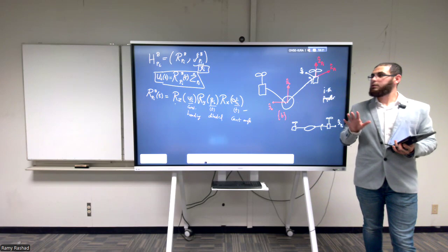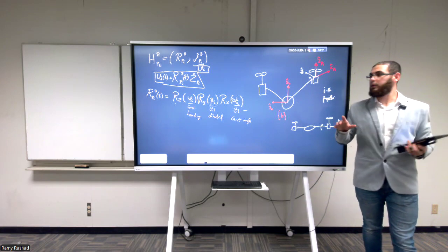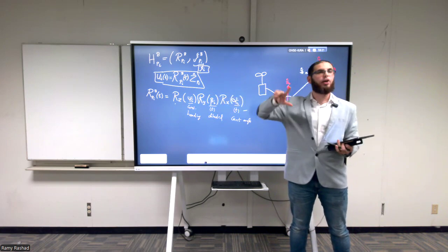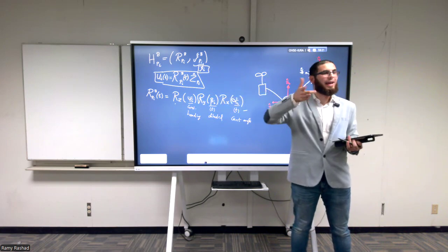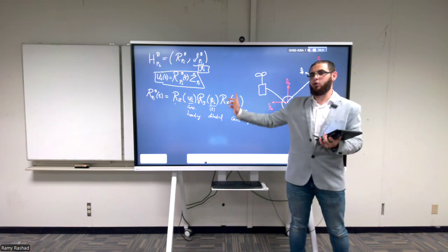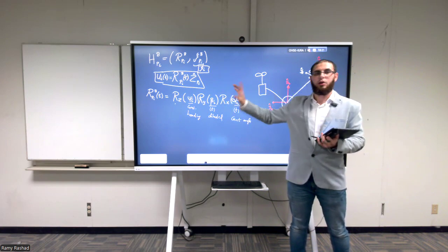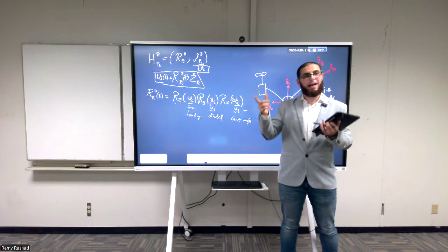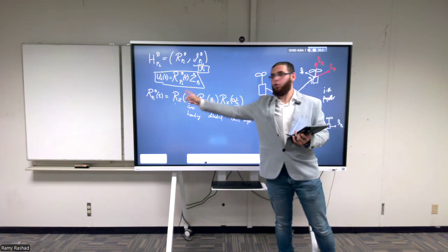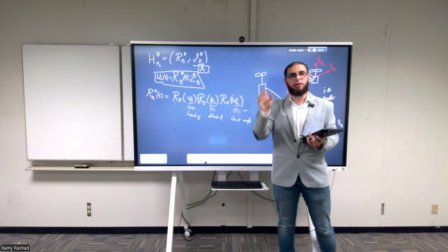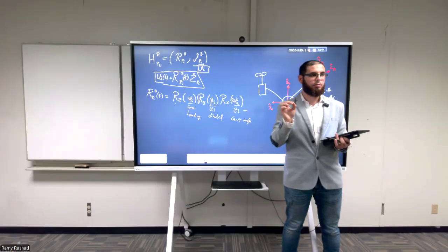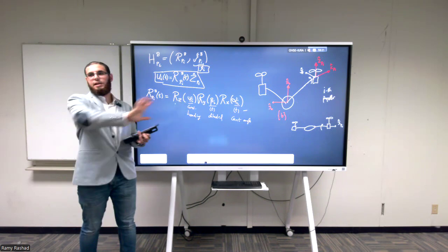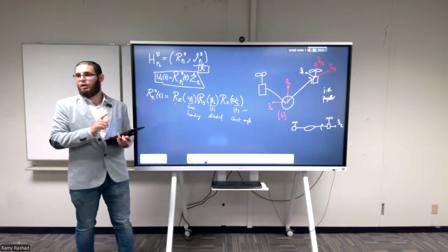So the short answer is the following. We're going to only use these angles to represent the R matrix, not the rate of change of the R. So we're not going to do any velocities with these angles. Going back and forth between these angles and the R is okay. Going between the rate of change of these angles and the angular velocity, this is where singularities happen. Okay? So this is the short answer. If you already know what I'm talking about, it makes sense. If not, just take it as one way of writing the rotation matrix.